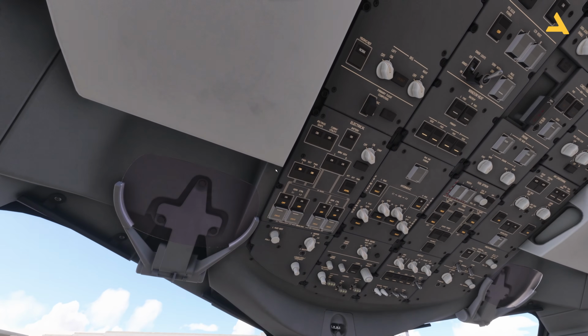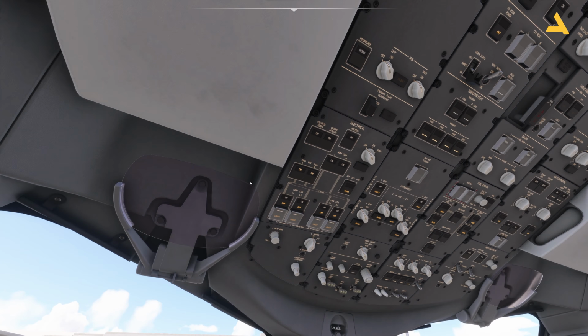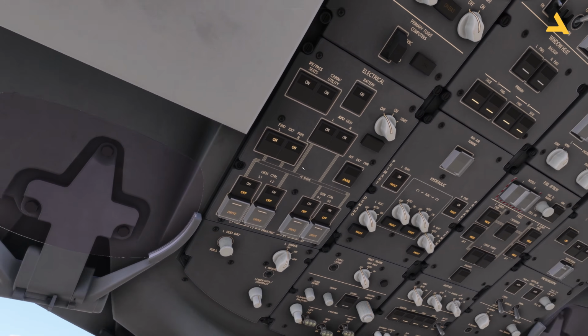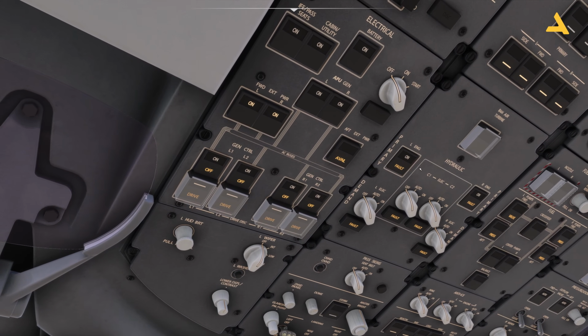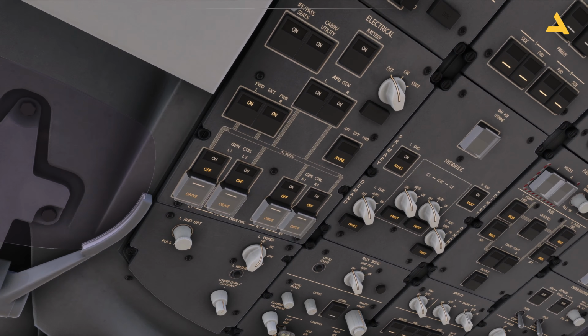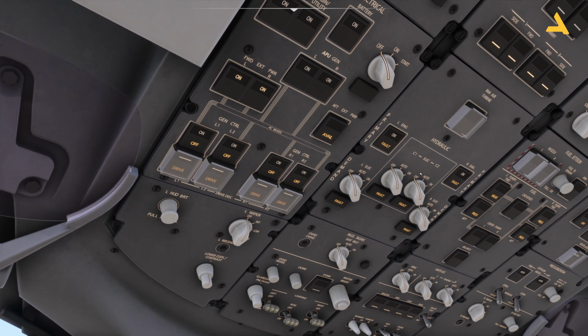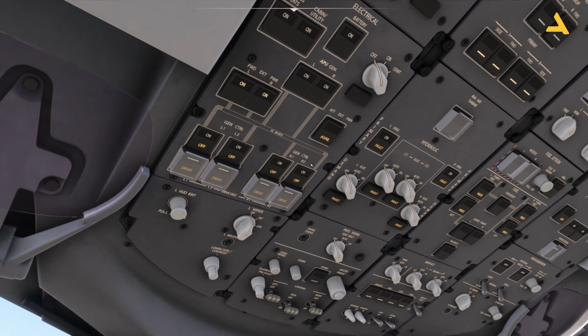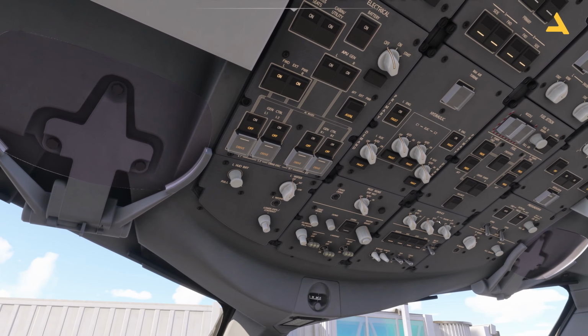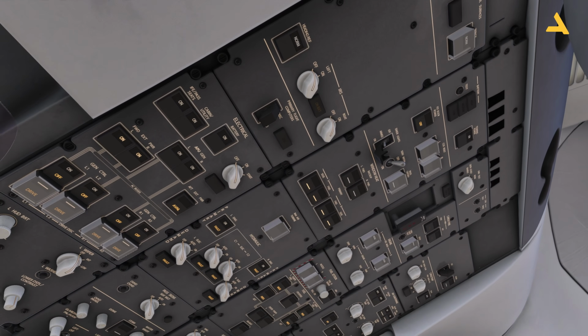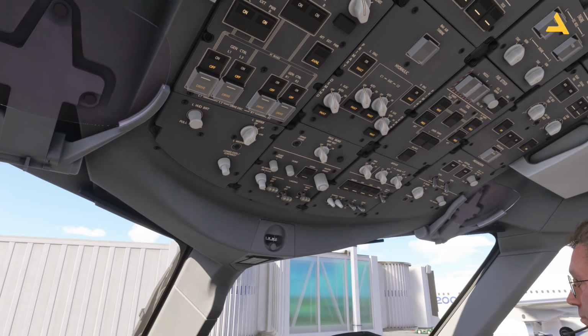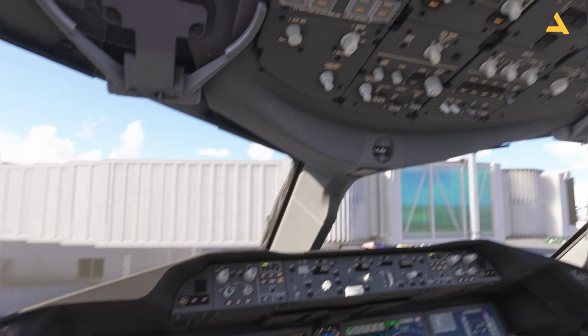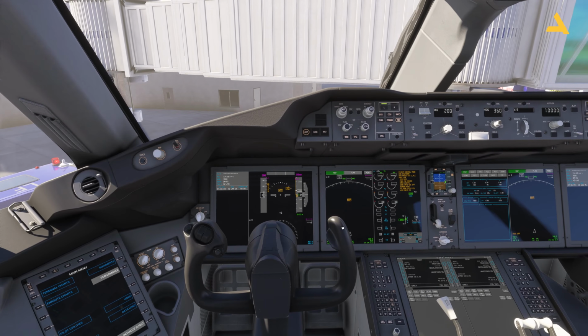Now, there is one more thing that you have to just ensure, that the hydraulic pumps are off. You have these primary hydraulic pumps. They should be on, but the C1 and C2 electric pumps and demand electric pumps, they're off. And that's it. Anything else? No. So before I begin, I will configure the FMC.